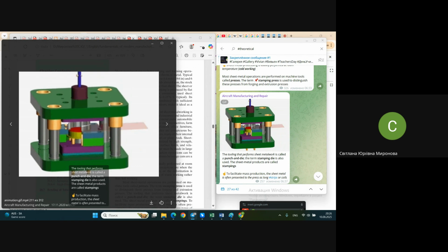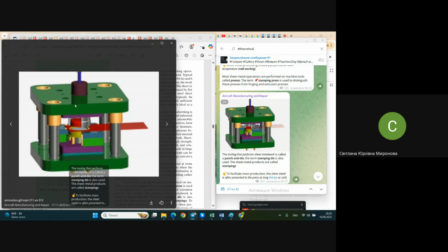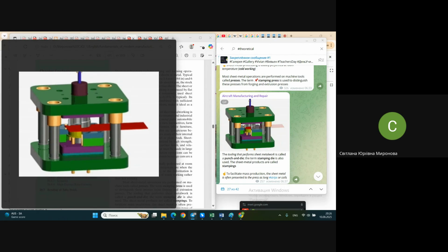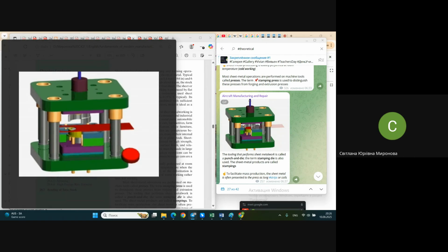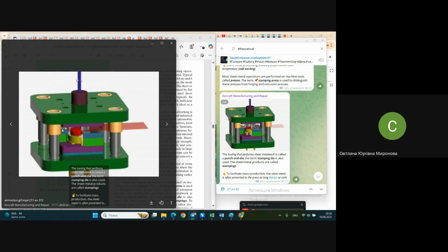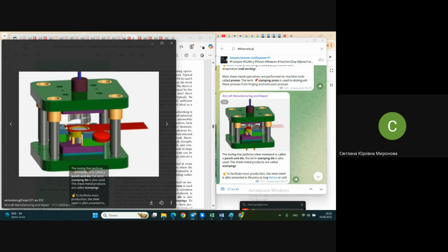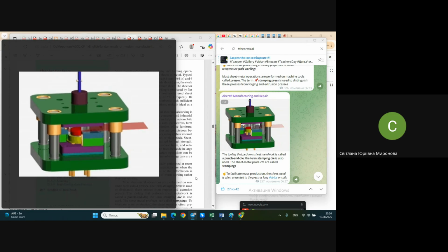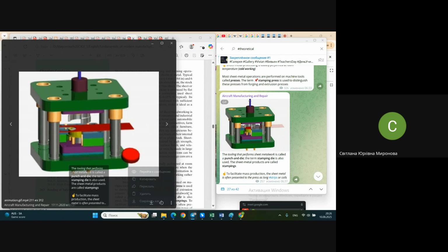The story is that all this tooling is necessary to direct two halves of the tool, punch and die block, with respect to each other. And one more group of elements in this die is necessary to direct the strip with respect to the tool. The strip, you see, is of red color. On the back side, at least you see a couple of pins there, but besides pins, there may be some additional devices that are necessary to direct them one to another.